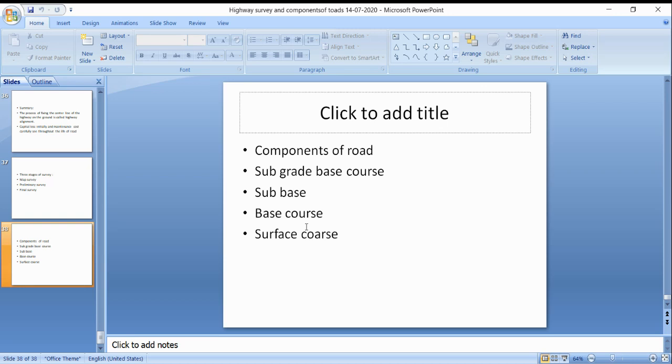So we can use the naturally provided slope at the time of the survey. In marshy areas it should be about 300 above, so the formation from the road survey can be provided up to a height of 300 above.